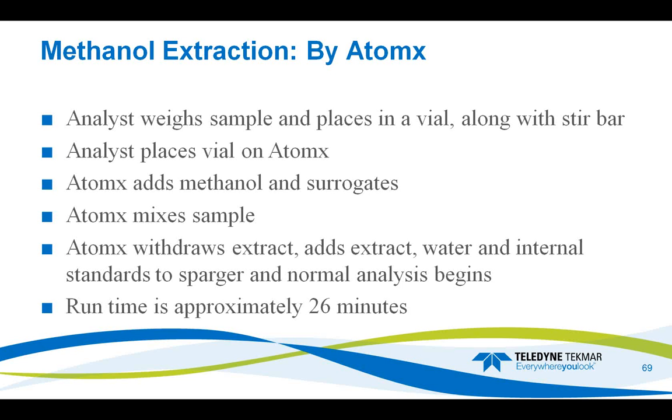The Atomx will add the methanol, surrogates, and internal standards, mixes the sample with the stir bar that was added, withdraws the extract, whatever amount you set it to withdraw from that sample, depending on what you anticipate the concentration being, adds it to 5 mils of water, and then purges it in the sparger, just as any other liquid sample. And the total runtime to do all of this is approximately 26 minutes, which is pretty good.